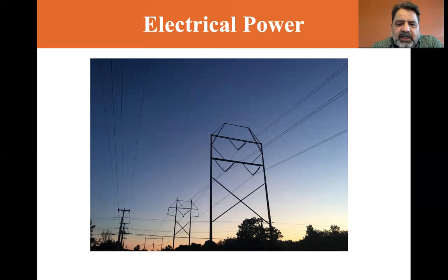Well, the utility companies decide to use low currents with high potential, so that you have power equals I squared R. The resistance of the wire is fixed at a relatively high value for economic considerations. So the I squared R loss is reduced by keeping the current I as low as possible.